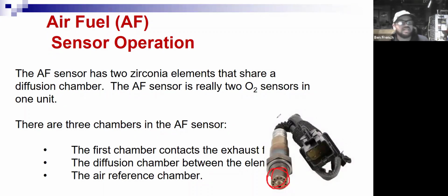They run in the neighborhood of 1200 plus degrees. So they tend to eventually burn themselves out. And sometimes they get themselves really stuck in those exhaust manifolds. So they become really hard to get out. And I've had some cars where I just had to replace the whole exhaust manifold with the air fuel ratio sensor, replace both those items to get the car fixed.